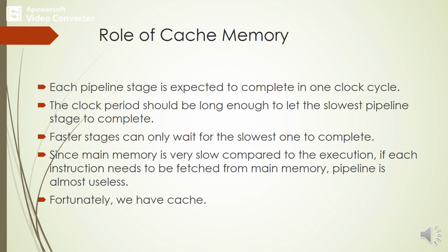So we can divide instruction fetch and processing into steps that are more or less equal in duration. Each of these steps is performed by a different pipeline stage, and the clock period is chosen to correspond to the longest one. We can overlap the operations, but while designing the clock period, we consider the longest task to be performed.